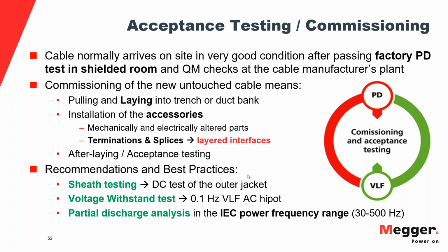So for a monitored withstand test, you should pay attention to your layered interfaces, terminations, and splices, because this is really the source of most of the failures in the cable. So it's much more valuable to do it with PD instead of tan delta. So I don't see much value to do this test with tan delta on new cable.